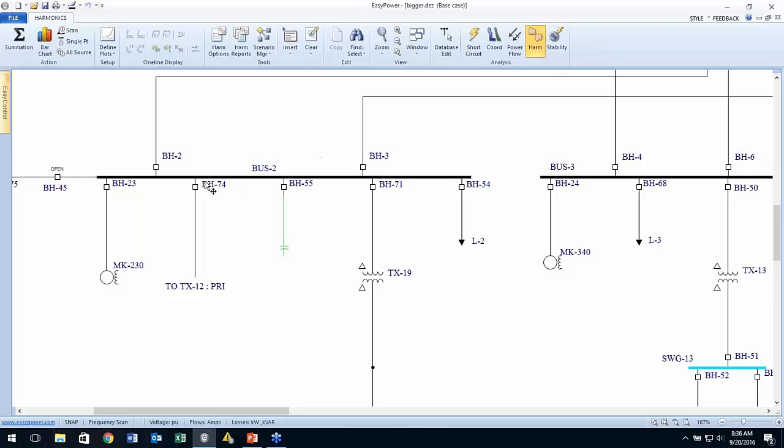This I would encourage your customer to do themselves: take regular voltage and current readings at specific times on a periodic basis and compare those with what the power flow projections are for each bus. The adjustments that could be made would be the motor loading, and potentially any impedance changes upstream that would affect those voltage and current readings.